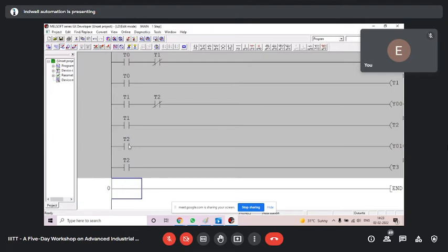So let me proceed. As you make a program in Mitsubishi or you modify an existing program, you can see on screen the color has become gray. It was white, now it is gray. I don't know what color you call it, I call it gray. It has changed the color. When the color is changed, it says compile, kind of like login. You did login in Codesys. The same thing it is asking you after making the program, you have to compile it. That is convert here. Look at the screen. Can you see this convert here?